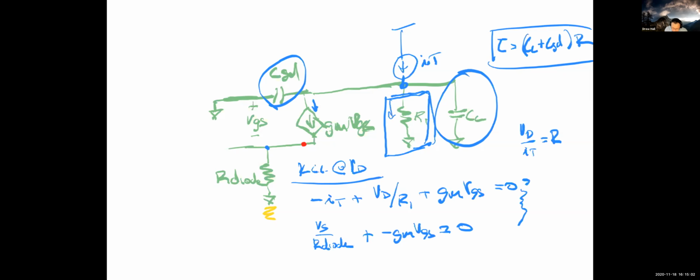But yes, essentially, we could be siphoning off some of the current into the transistor itself. We won't know until we solve this set of equations. I guess my point is that it could be just RL, but it's not immediately obvious from the schematic. We actually need to solve this out to prove what the driving impedance is.